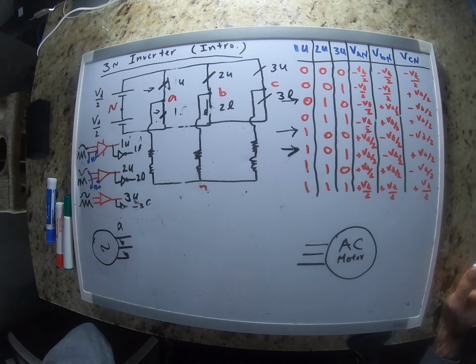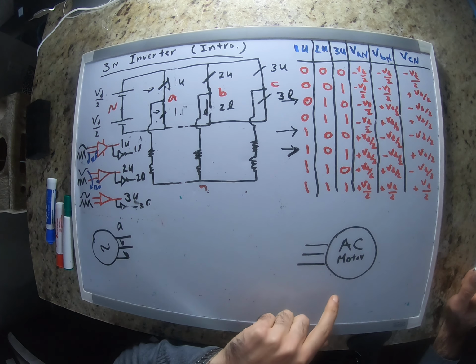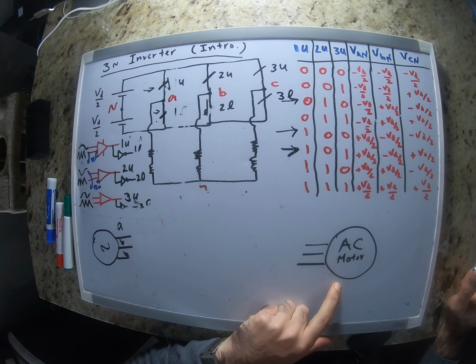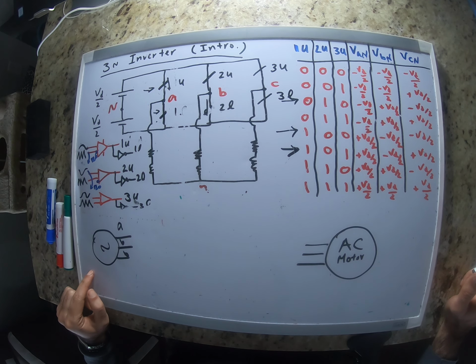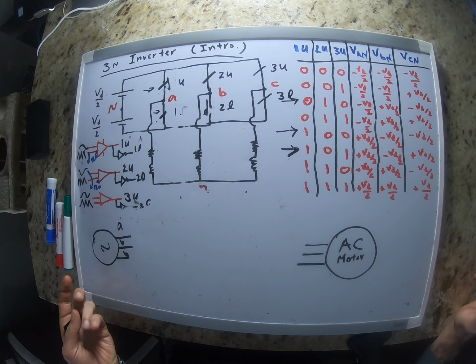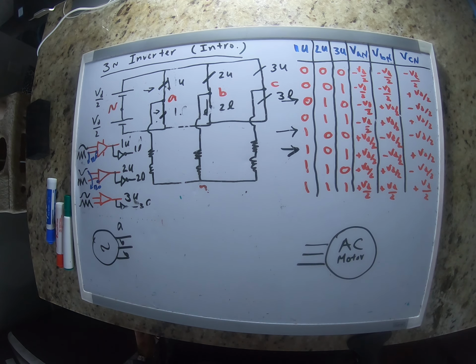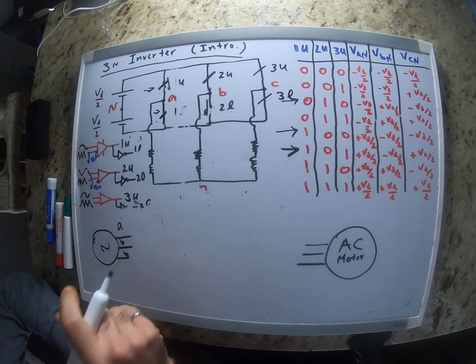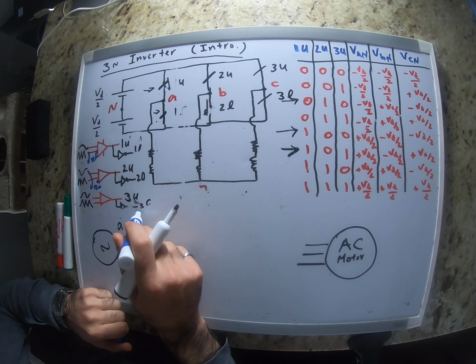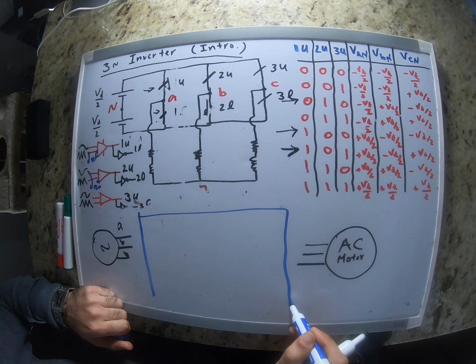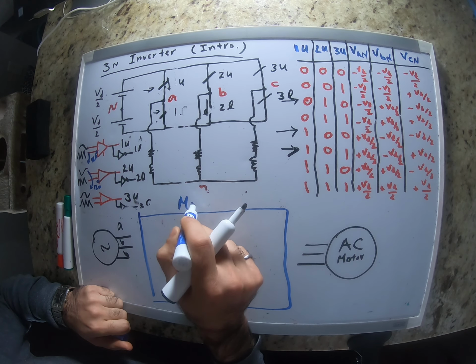But for an AC motor, it's not that simple, because the speed of the motor is determined by the frequency that you supply it with. Now the frequency of the grid is fixed, 60 hertz or 50 hertz, so we can't change the frequency of the grid. So one thing that we do is using something called drives, motor drives.